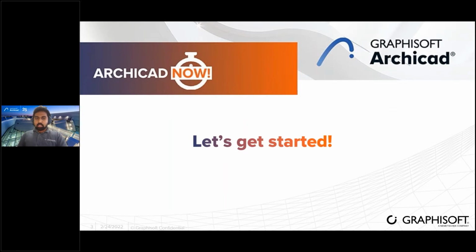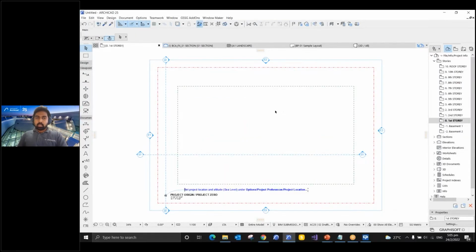All right, so I'll directly go to Archicad and show you how to set up the project preferences, the project structure, and the translators for IFC and DWG. Here I'm using the BCA template as a base, using which I'm going to explain how to set up all these functionalities in your project template for your company.